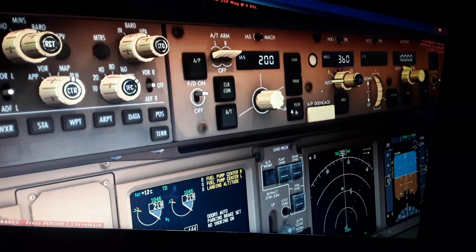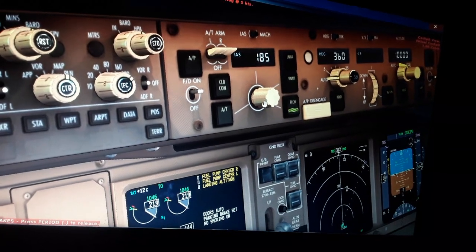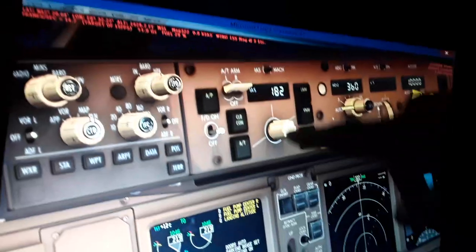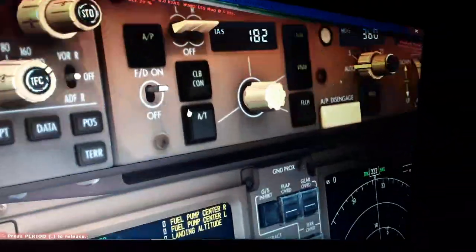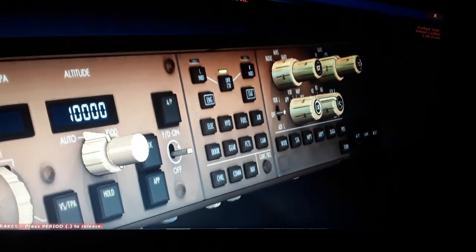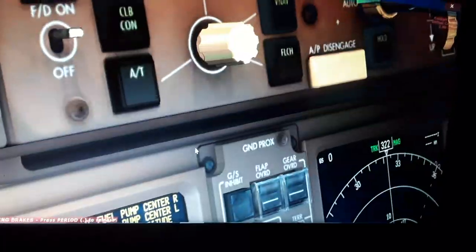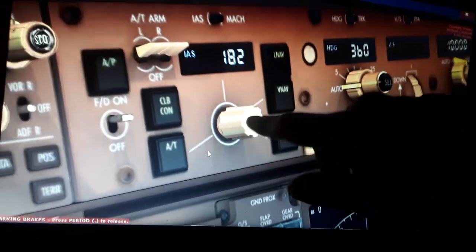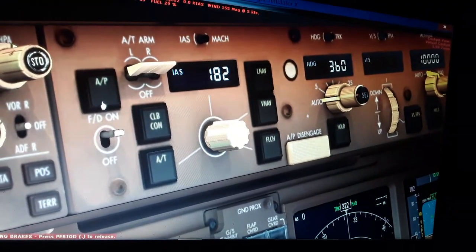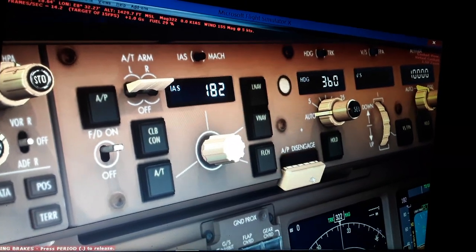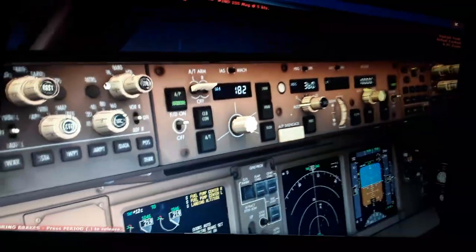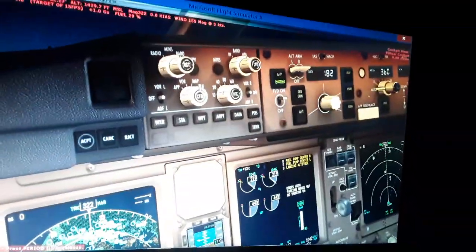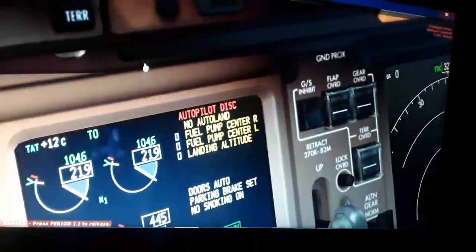The flight director also, the flight level change. The flight director off disengages this. So we can have both flight directors either side. So this is depressible also, the autopilot on and off. Like this, you press out this switch. So you need also to cancel the warning here. So we have the autopilot disconnect like this.